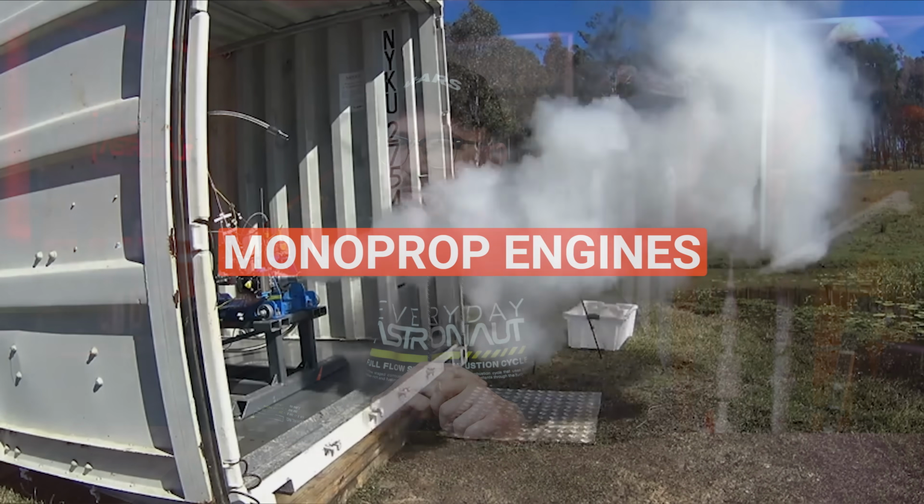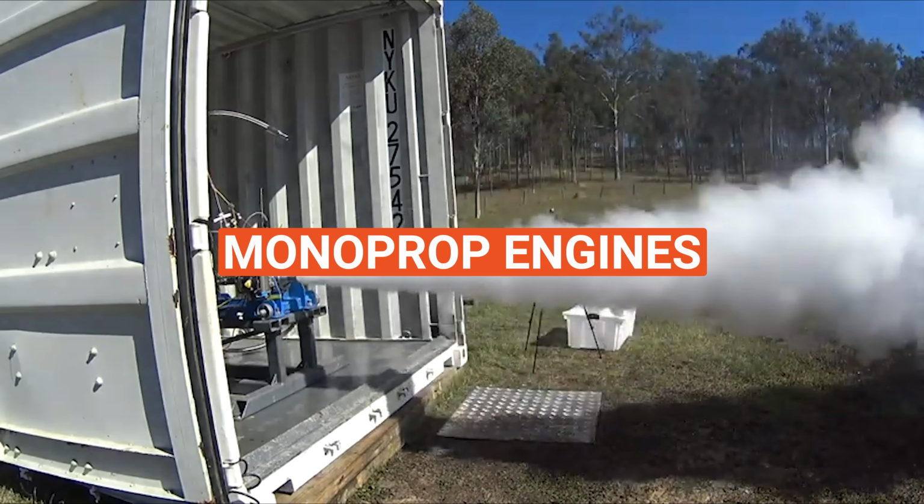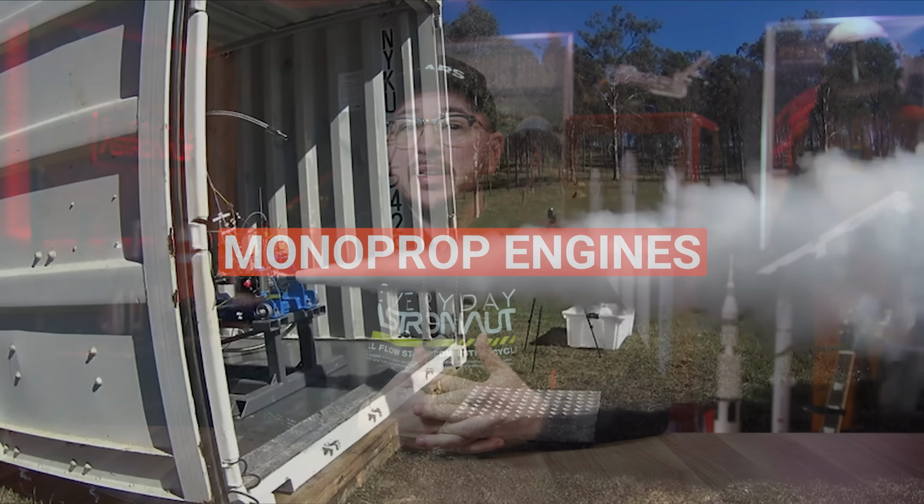But now, what if instead of just having that high pressure gas flow straight to the engine, we instead had it pressurized and push out another propellant that could react and expand to offer higher performance? Well, that's definitely an option. The next most simple engine design is called a pressure-fed engine. This is similar to a cold gas thruster in that it has almost no moving parts, just some valves. But it can offer much higher performance by tapping into the chemical reaction of the propellants.